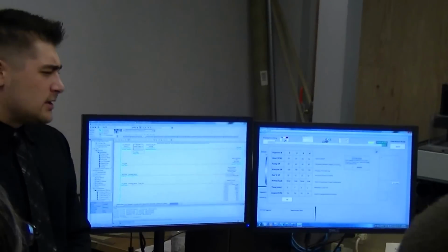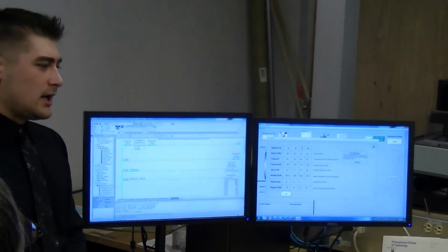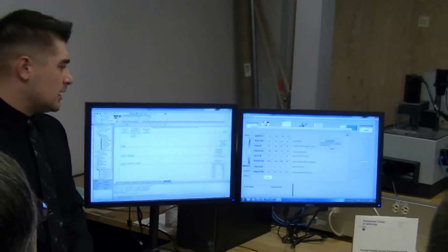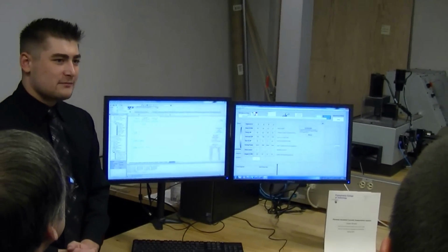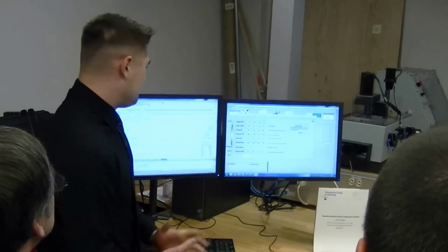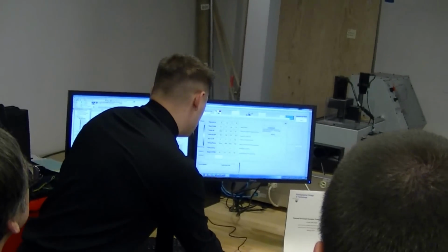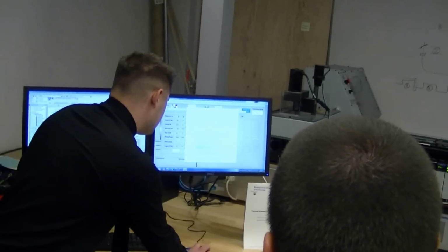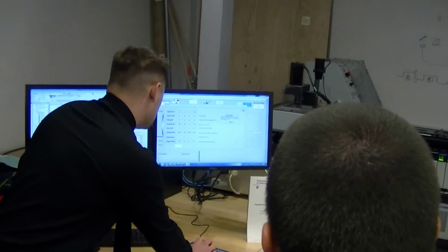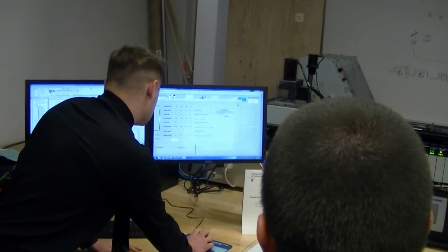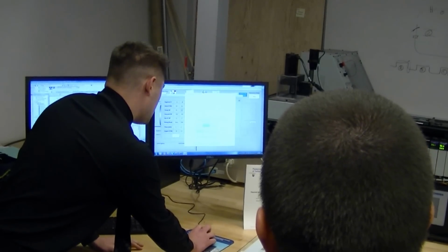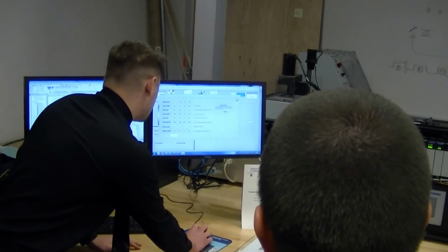This system can operate to 250 degrees on a 2,000 watt heating element, and without further ado, I guess we can pick some values and start this. So for the sake of demonstration right here, we'll go to a set point of, say, 50 degrees C in segment 1. We'll open up the gas valve for 10% of 40 psi. Segment 2 will soak at 50% for 2 minutes.